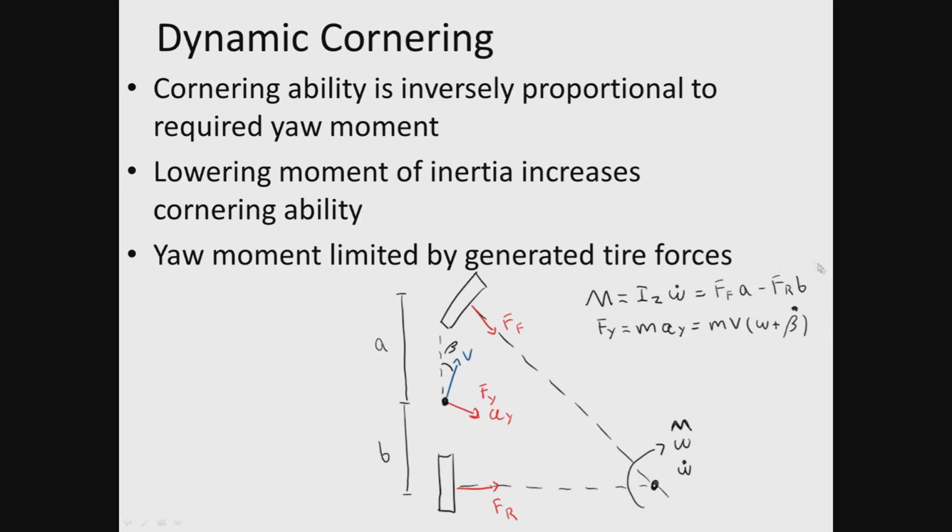This is something you need to go through on your own at some point and get a more in-depth understanding of the equations. But the general idea here is that we are now concerned with the moment that we're generating around this turning center. So the car is still following that same linear path here along velocity b, turning about the center of your corner here. For that point, what the corner radius is. The corner radius may change as you go through. It's easiest if you consider it to be a constant radius and you get that static turning center.